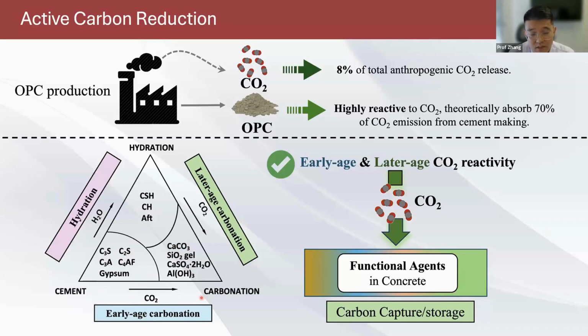The beauty of carbonation is the fact that even when the concrete or cement has been hydrated, it still has CO2 reactivity, CO2 reaction potential. We call it later age carbonation. So CSH will become calcium carbonates and silica gel. Calcium hydroxide will become calcium carbonates.